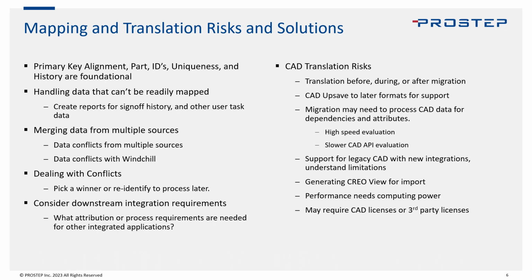The migration also might need to be able to process CAD data and understand all the dependencies behind it, especially if you're coming from a directory that has different CAD files on it, and that's your source data. You have to do a scan of that data, but then you need to also look in the binaries of those CADs and understand all the dependencies, like the files and the attributes that are in those as well, so that you can build that data web of dependencies to be imported into the PLM.